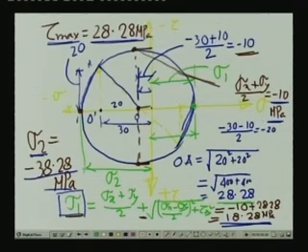Also, we can evaluate the position of these planes, the maximum and minimum normal stresses, with reference to the plane. Now, this is the plane which is representing the vertical plane. The normal to the plane coincides with the x axis, which we call the x plane. Now, with reference to this particular plane, if we go in the anti-clockwise direction, this particular angle will give us the value, half of which is the orientation in the physical plane which locates the maximum principal stress, and perpendicular to that is the plane where the minimum normal stress acts.